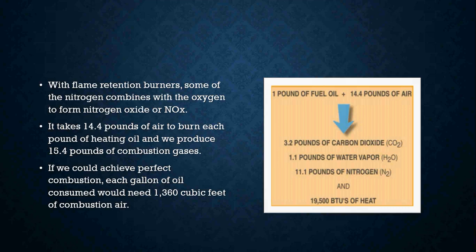For each gallon of fuel oil consumed, you are going to need about 1,360 cubic feet of combustion air in order to achieve perfect combustion. By perfect combustion, we mean all of the fuel is burned off 100%.